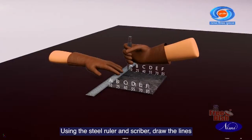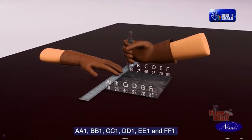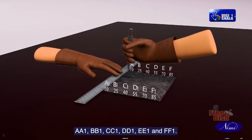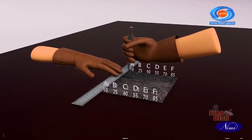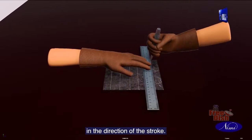Using the steel ruler and scriber, draw the lines AA1, BB1, CC1, DD1, EE1 and FF1. Draw towards you while tilting the scriber in the direction of the stroke.